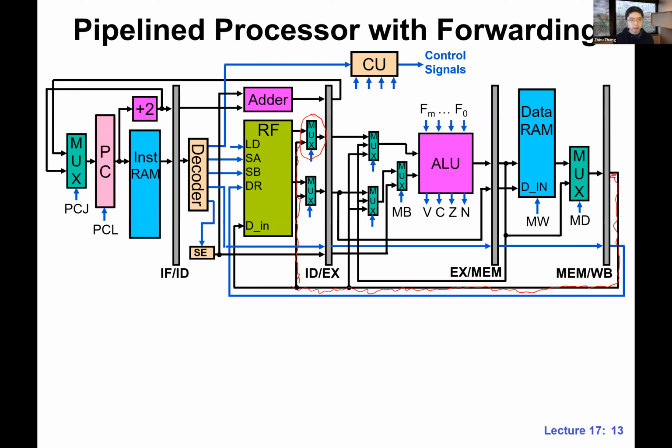We also need some additional muxes, of course, for data B, because in some cases data B may cause a data hazard. And we have some additional muxes in front of the ALUs. That's where we choose whether we take the one from the previous stage or the forwarding path. Again, there is some forwarding path from the MEM stage, and some forwarding path from the WB stage.